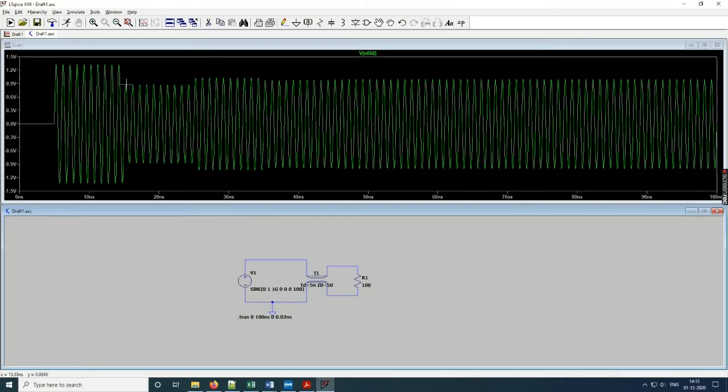So the change at the load will start happening from 50 nanoseconds onwards, because of one round trip, load to source and again source to load. Then this short circuit source will reflect the entire reflected wave back towards the load with a reflection coefficient of -1. So after 50 nanoseconds, the amplitude of the load voltage again dies down.